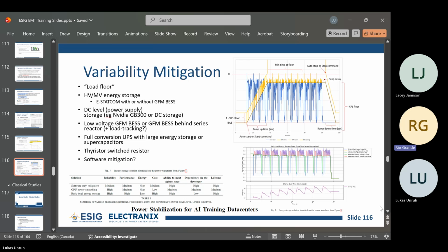After about 7 years of standard development for the original PR24, it basically got treated as a protection setting standard. So everyone put their protection directly on the bounds of that curve, which means every site has the same protection settings, which is the same problem you're saying: everyone trips off at the same event.